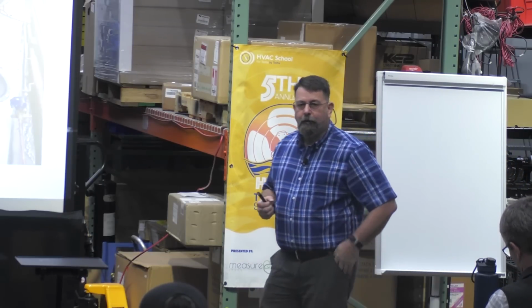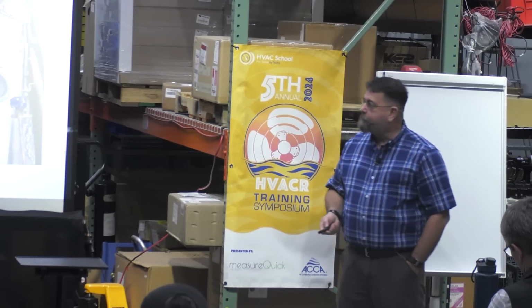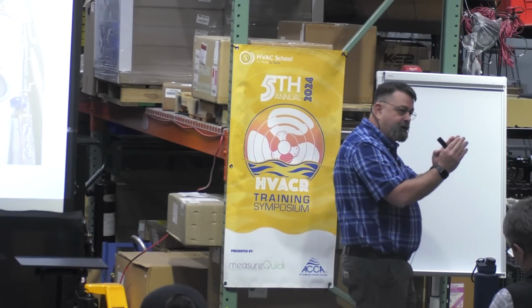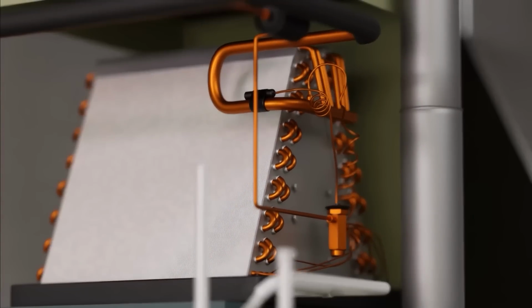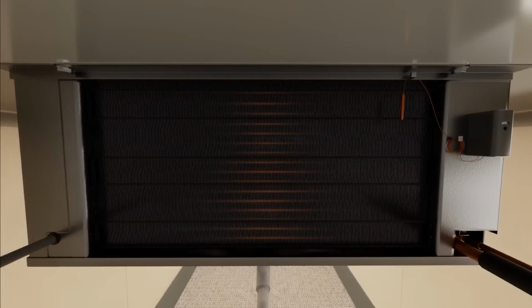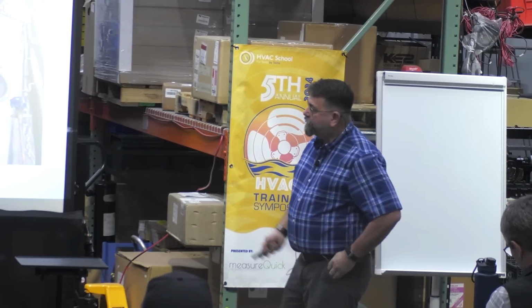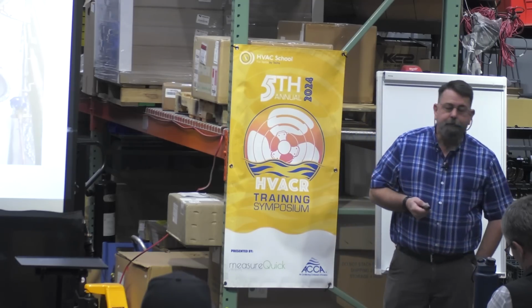So the colder we get, the more gap we have to have because we're going to grow more and more snow and frost, right? If the frost on 2 fins grows enough that it touches, I've got a stopped up evaporator, right? It's the same thing as your evaporator full of cat hair and dust. How well does that cool? Yeah, no, it turns into a block of ice. Well, that's what's going to happen to mine too. It's going to turn into a giant block of ice. My defrost won't be able to handle that much, right? Once I shut off that airflow and it starts growing ice, I'm out there with hot water, right? Trying to melt it out. It's a service call, okay?